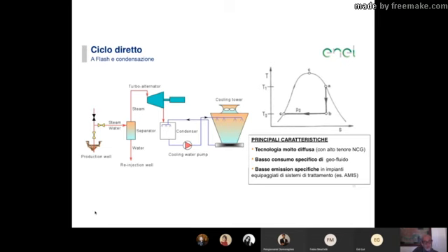Another way to do it is to start producing the flash within the well. To avoid deposition and scaling, so usually it's calcium carbonate, the main crystal that forms. To avoid producing solids that will clog up the well, you need to add to the system usually acids or inhibitors of precipitation. So you bring to the surface